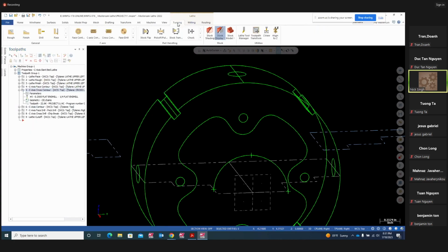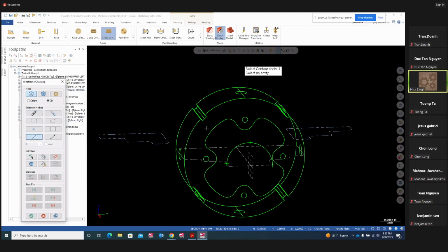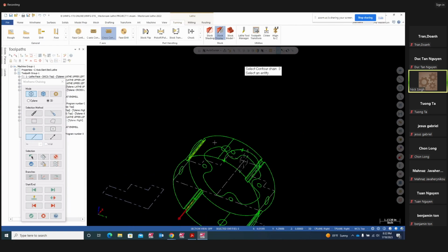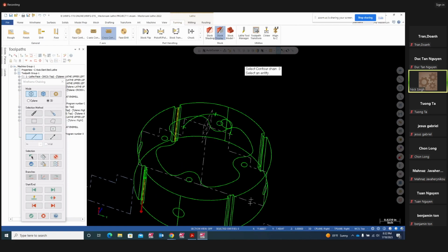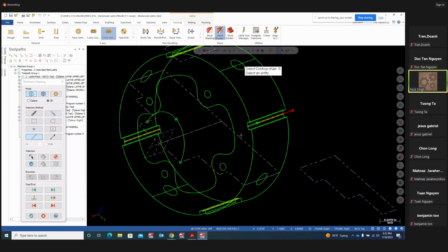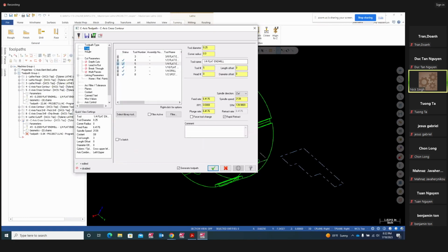And that toolpath is right here, C-axis cross contour. When you select that cross contour, you're going to select the single. You will be selecting 1 and 2 and 3 and 4. Hit OK. Hit OK. And your tool is going to be your 1/16th flat.